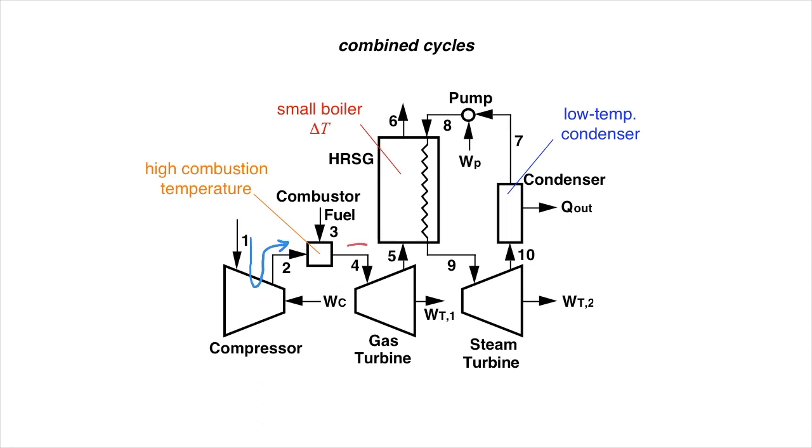This energy of combustion is captured at high temperatures in a gas turbine engine, which produces exhaust at 400 to 500 C, the starting point of the process we analyzed previously. By using this exhaust to boil water in a heat recovery steam generator and running a second steam cycle, the overall exergetic efficiency can be as high as 60% or higher.